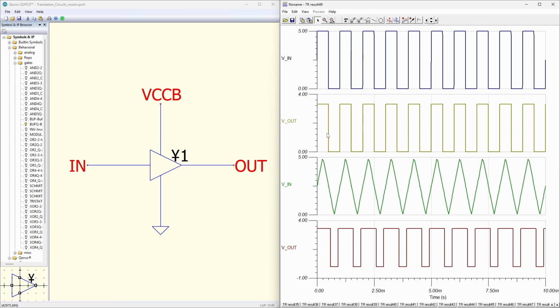Generally speaking, the results are very good. And the one thing you really have to watch out for is that the inputs on these have limited capabilities. In the datasheet, it'll tell you what the absolute maximum input voltage range is, and many times it's going to be 5 volts. Sometimes it can be very beneficial to use one of the previously mentioned down translation circuits in order to protect the input of a CMOS buffer like this, and the buffer itself is what's going to produce a nice clean square wave output.